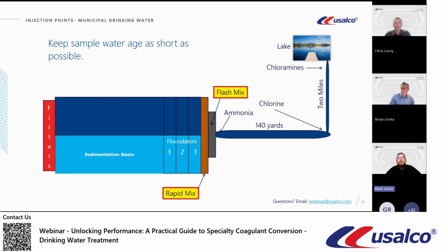We actually ran a study where we had the sample sit for 2 hours, 1 hour, 30 minutes, and pulled immediately. And every single time, the water that sat for 2 hours had significantly better results, and had a different product that was optimal for that water. And that again goes back to the longer it sits, the more precursors are removed, your pH changes, temperature changes, and everything else. So it's super important to grab your water and immediately run the test on it.